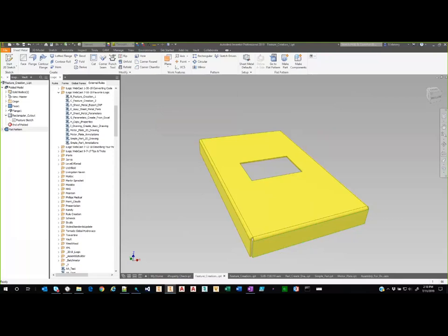So let's look at some other sheet metal stuff. One is exporting flat patterns to a DXF, right? A very common thing. Just about anybody who works with sheet metal is probably familiar with it. You need a flat pattern for the manufacturing process. It's a very tedious thing to do on a one-by-one case basis. Therefore, it's a great thing to do with automation.